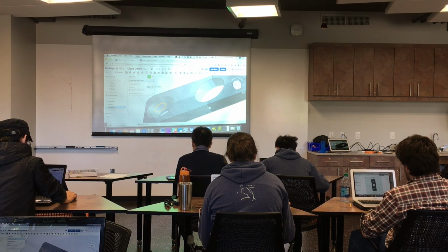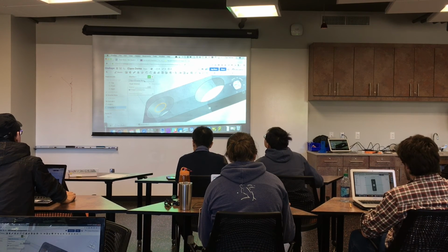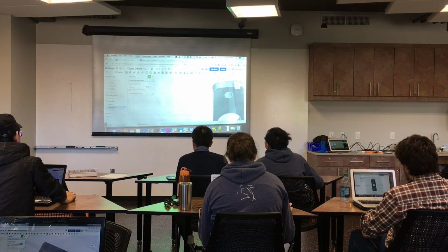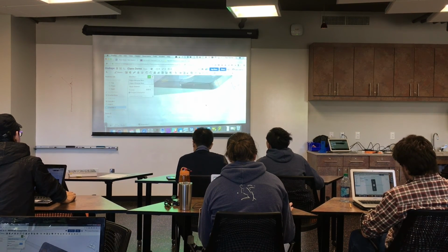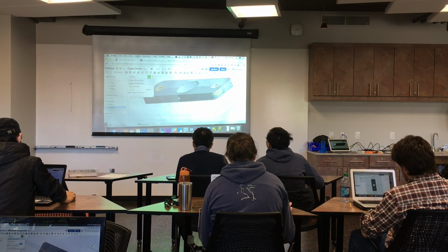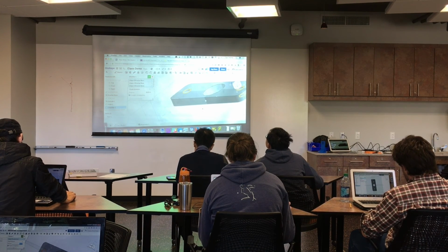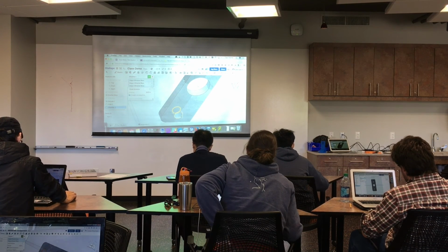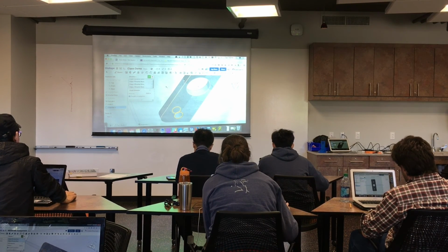So let's chamfer it to 20 thousandths. If you do that and then just click somewhere up in here, that looks a lot better. So I'm going to go ahead and chamfer both sides of those holes. Like that.